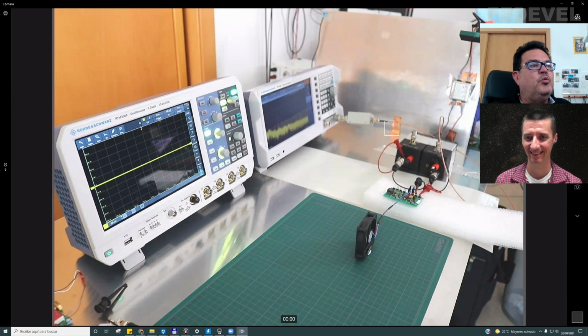You can see here I am using tape too, in these points. This is a way to connect the different elements of your setup between them with low impedance. And the shield of the cable, which is connected to the spectrum analyzer, is connected to the ground again, from the schematic you drew.